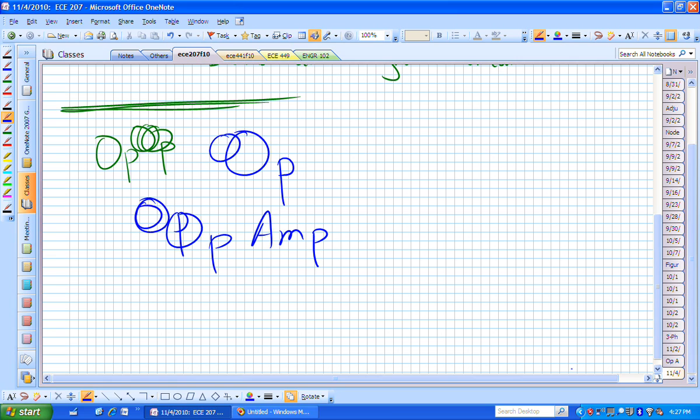Is that okay? If I now write KVL for that particular loop, what do I want to call it? Let me call that M. I'm running out of creativity here. So if I now say KVL around M, I could now say that that's minus V sub I plus R sub 2 I sub 2.